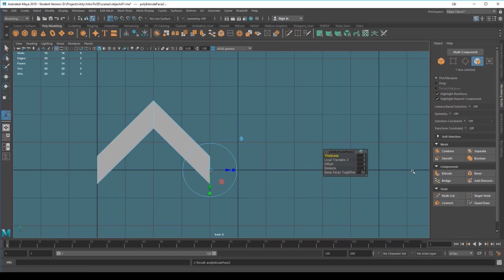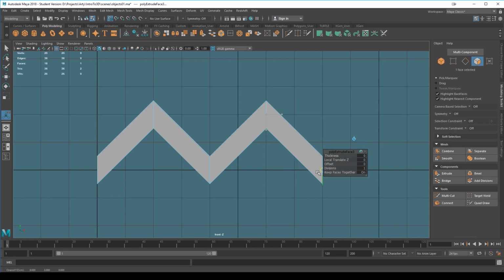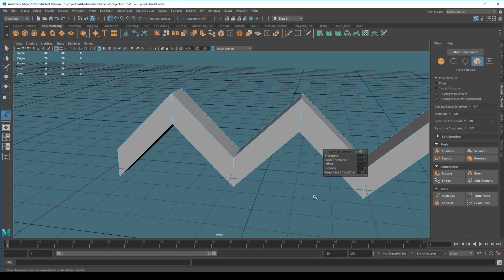Alright, so let's extrude another face. Just bring this out, W. I'm just going to hit G to repeat that extrude. And we'll just repeat this a few times. So G to repeat that extrude, G, G. And just keep repeating that a few times. Let's see, do I want to end? I think I'll end it with pointing upwards, so it starts down and ends up. Looks fine.